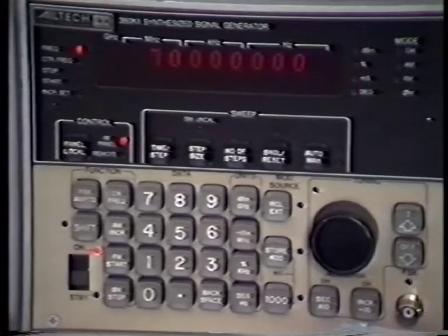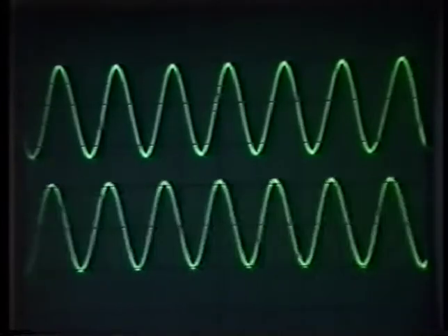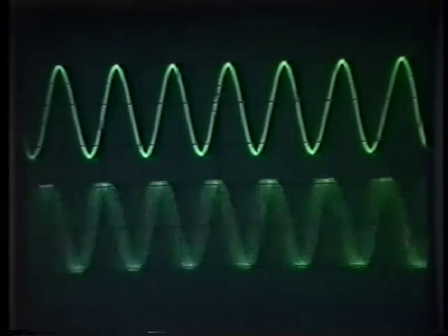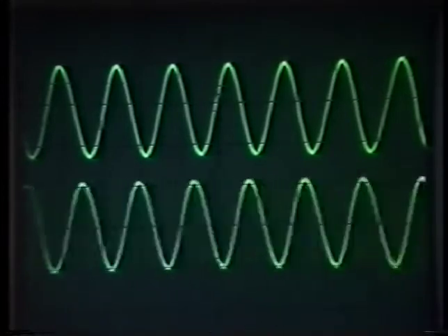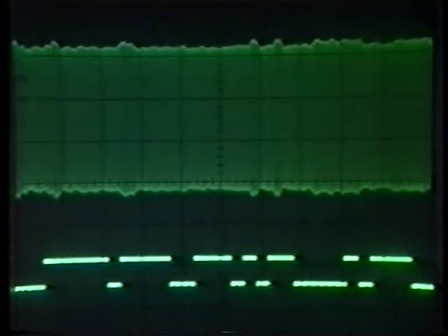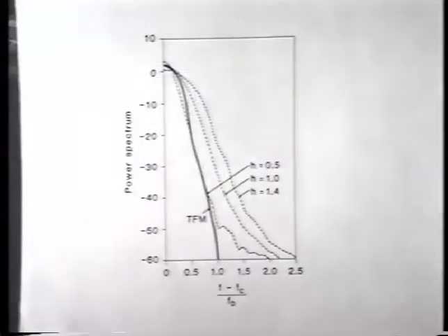The 70 MHz carrier frequency is generated by this unit. Here we can see the effect of phase modulation, which corresponds to a time shift. The resulting envelope is almost constant. The power spectrum will be wider as the modulation increases.